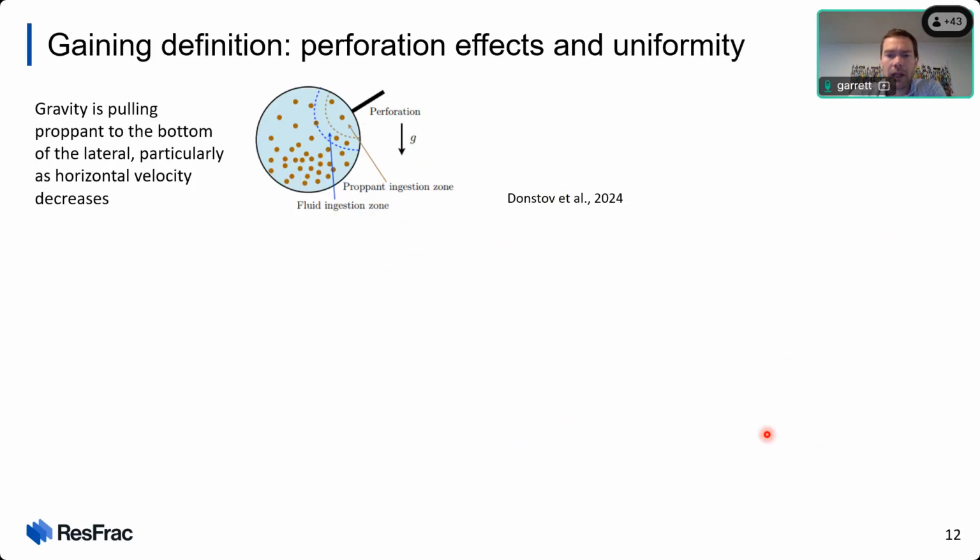All right, the final realm of diagnostics that I think is really impacting modeling today and providing much higher detail on our constraints is perforation measurements. So DarkVision, EV cam, and a number of other technologies are imaging the perforations after treating these wells. We have a pipe, we perforate the pipe, we pump the frac, then we go in and image those perforations. We do so to try to understand where the proppant went and how uniformly we distributed that proppant across the lateral.